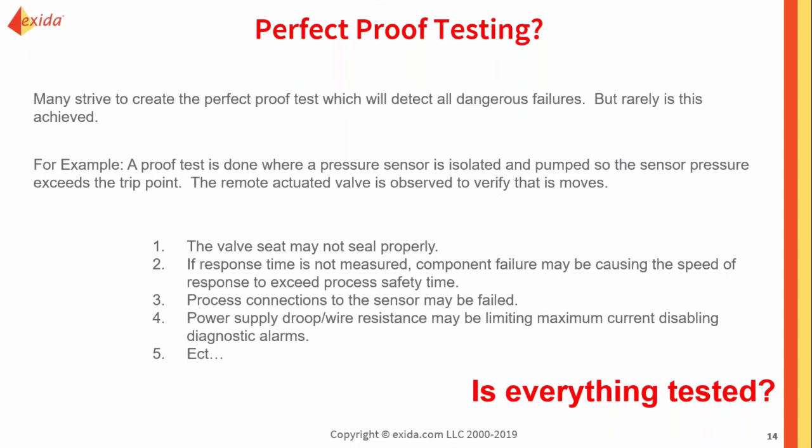Well, no one checked any of the internals of that valve. Were there damaged seals? Was it seated properly? What about the butterfly or the ball itself? Was that damaged, and working properly? What about the shaft? You might not know things like leakage or timing. If it wasn't timed, how important is that process safety time? What else could have gone wrong?